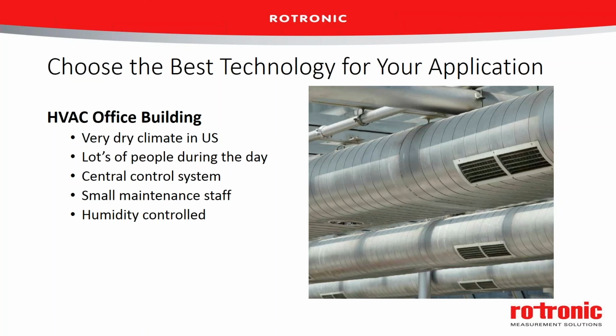A chilled mirror system, probably overkill for what we want to measure here, and cost is also going to be a concern on that, as well as the maintenance. A psychrometer, again, we're probably not going to be able to send that back to our central system. So that really leaves us with a capacitive system. And quite often here, we might also want to be looking at a real-time monitoring system. And most of the systems available on the market link up with capacitive sensors. So for this type of application, we're probably looking at a capacitive sensor, and that's where we'd start.